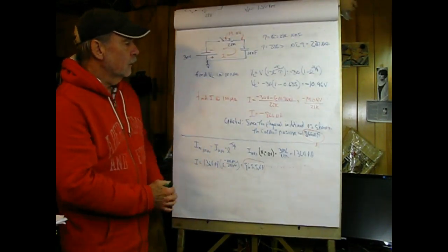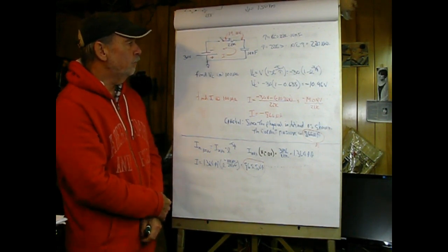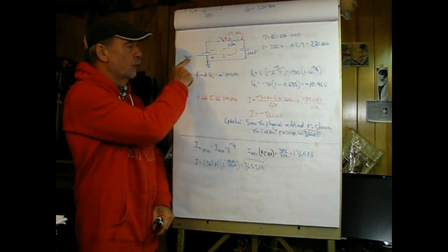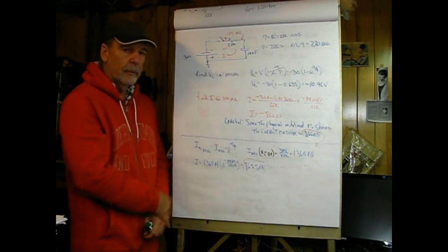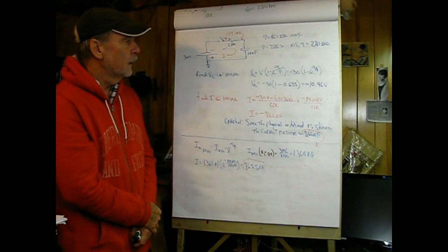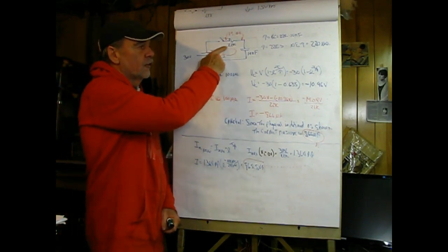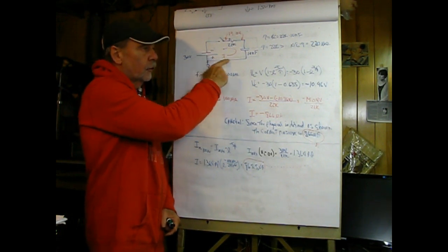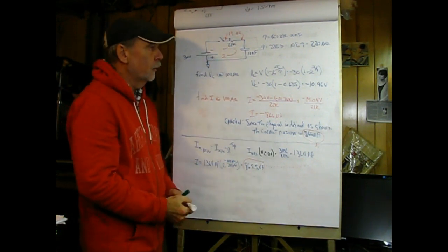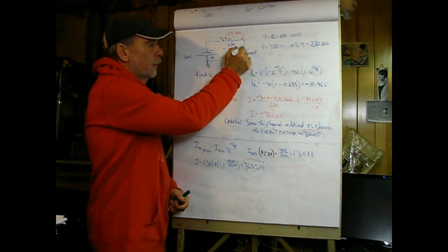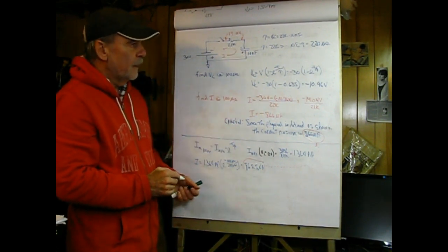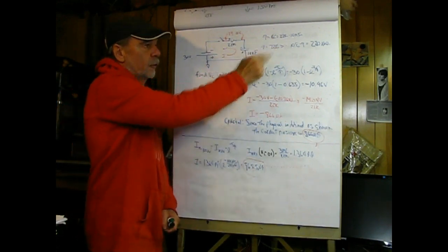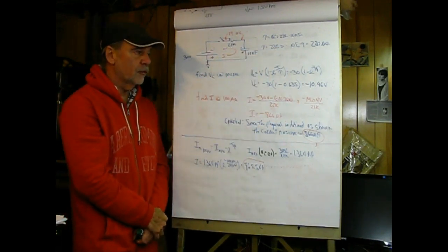And let's take a little look at this guy. This time I have a source which is negative 30 volts, and I just said 30 volts here because the symbol of the battery is saying that it's negative. And what I have drawn here is the physical current. So when the switch is closed, the physical current is going to charge the capacitor in this polarity, plus and minus. So my time constant in this case is going to be equal to 22K times 10 nanofarad, which comes out to be 220 microseconds.